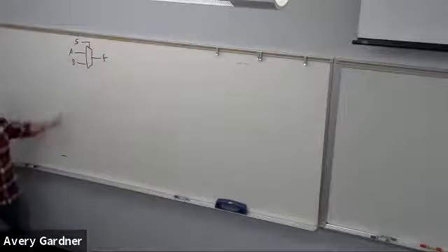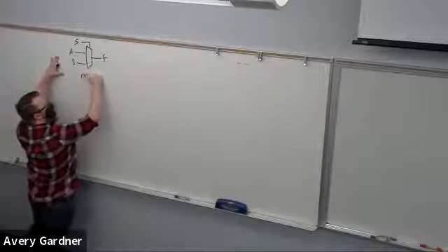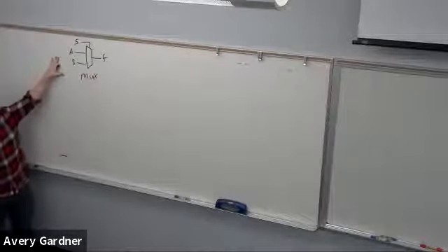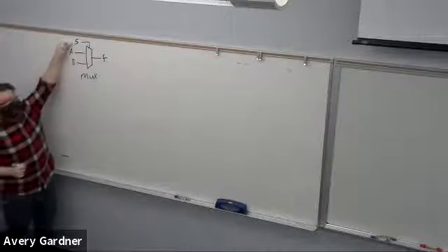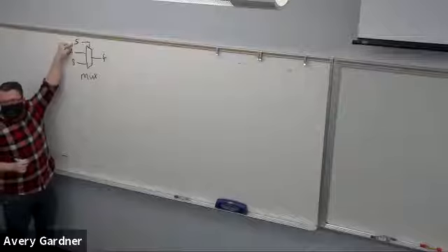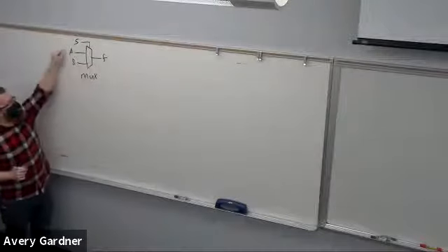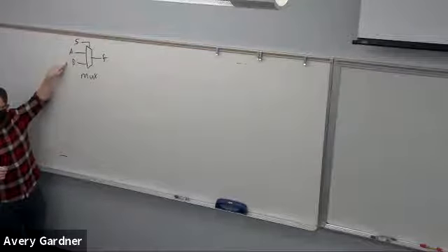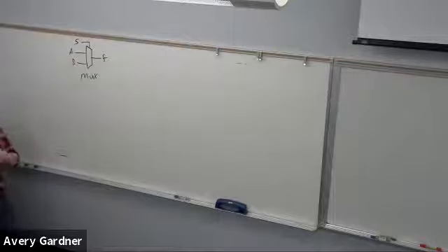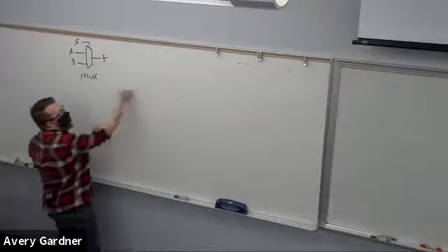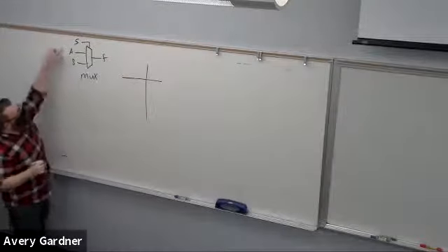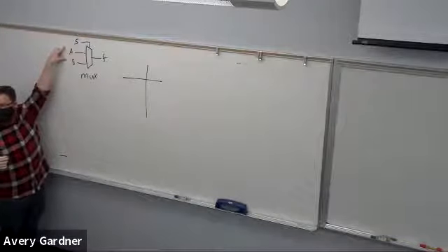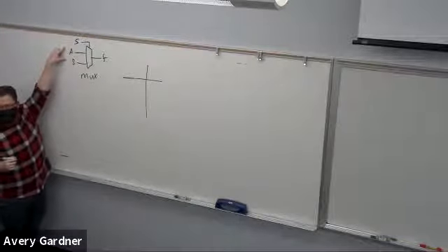We call this a mux or a multiplexer. So what this circuit does is it has S, a select signal, that chooses F to be either A or B. So it's changing the path. It's selecting one. This truth table then, we have 3 inputs. How many rows am I going to need? 8 rows, 2 to the 3.